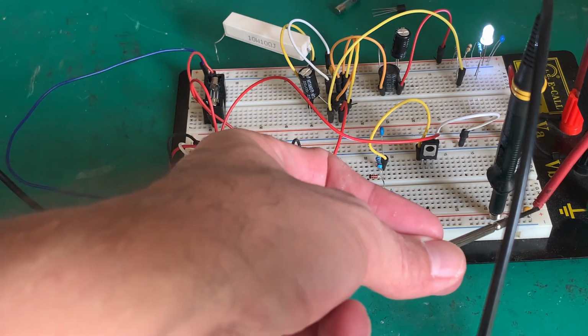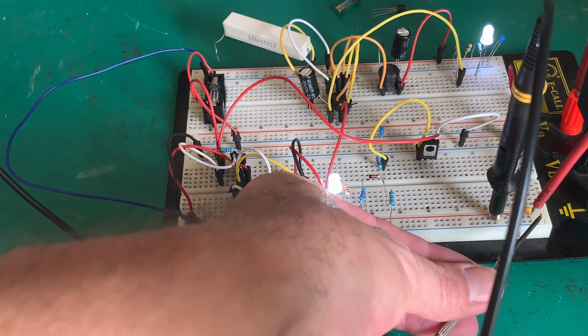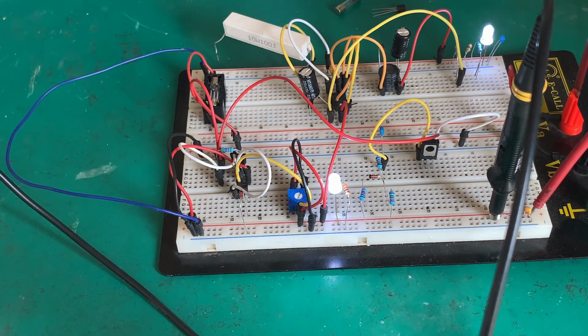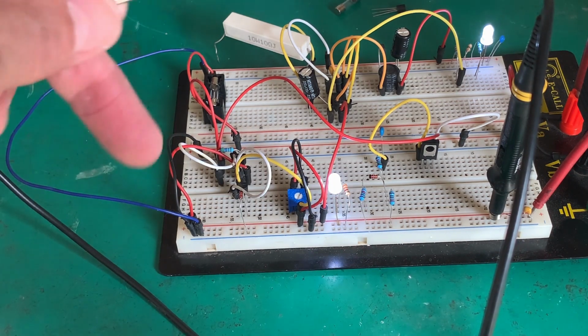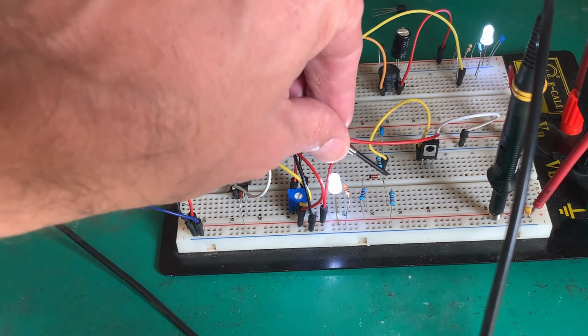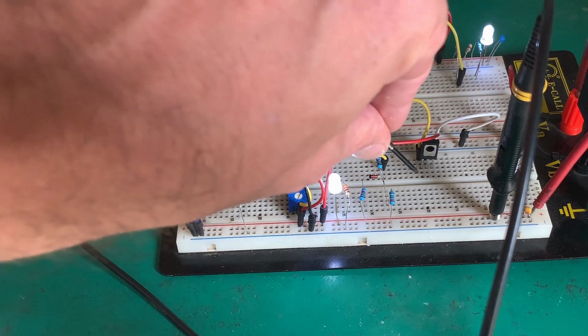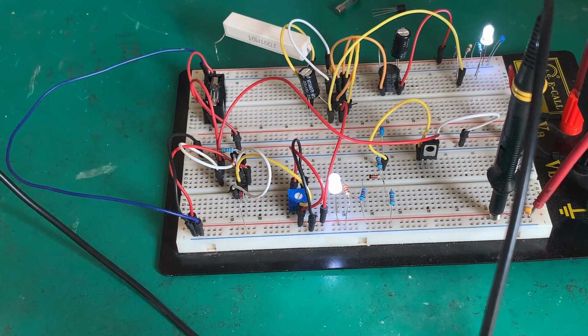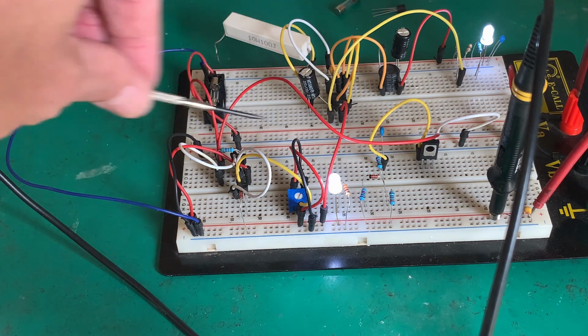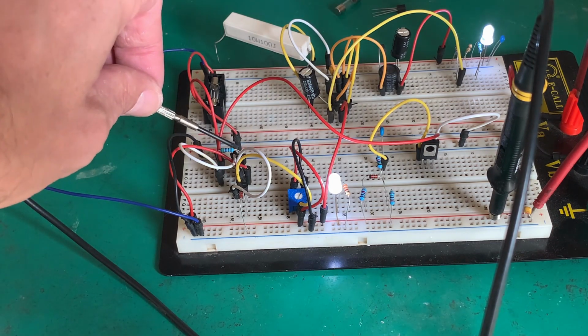So this capacitor is offering a couple of milliohms to that AC noise. So all that AC noise is going through that capacitor to ground. Anyway, interesting little circuit, the crowbar. There is our voltage divider with the current limiting resistor that's going to the gate. So if you're doing a series pass emitter-follower voltage regulator like this, make sure to put in your crowbar, because this thing has no protection.